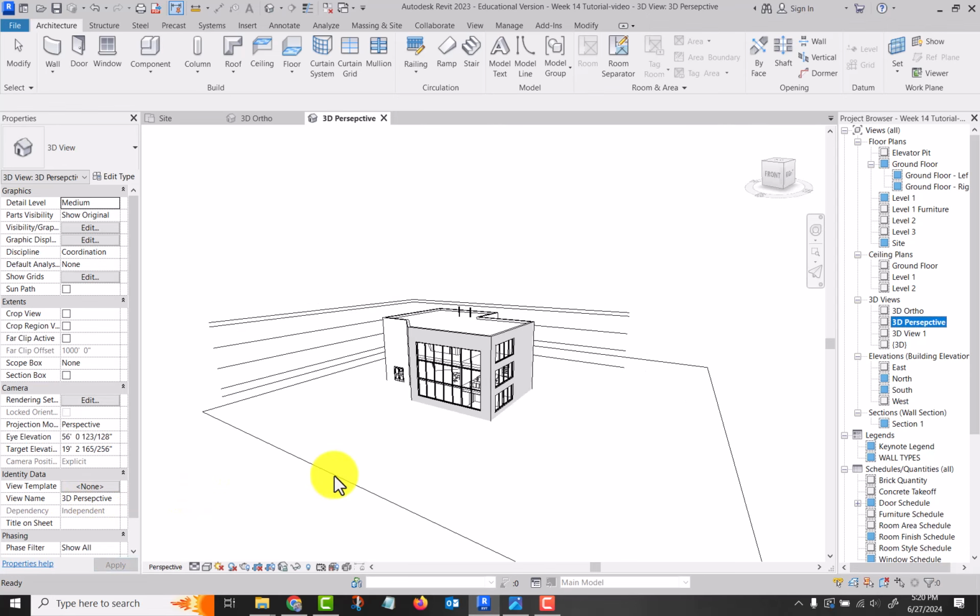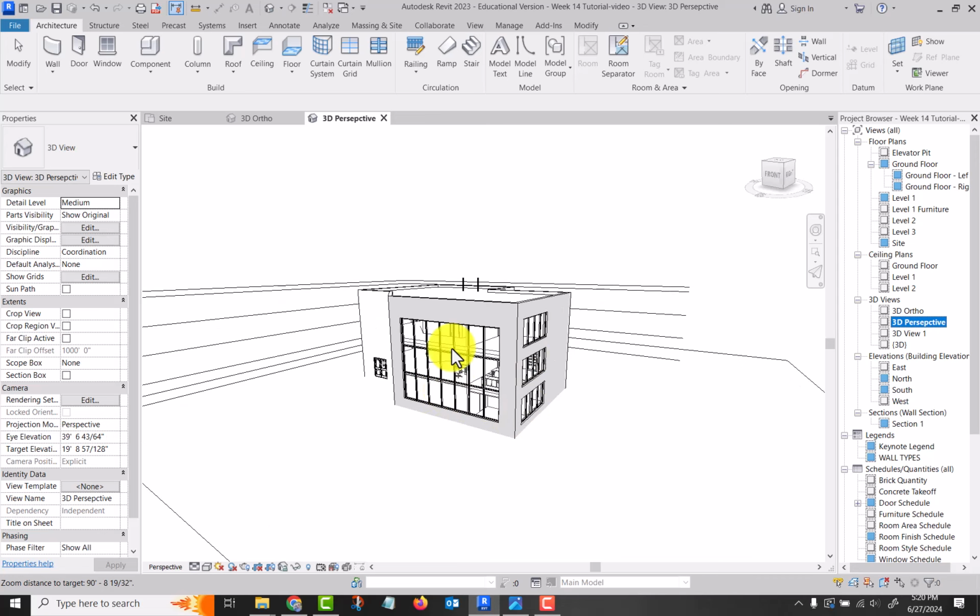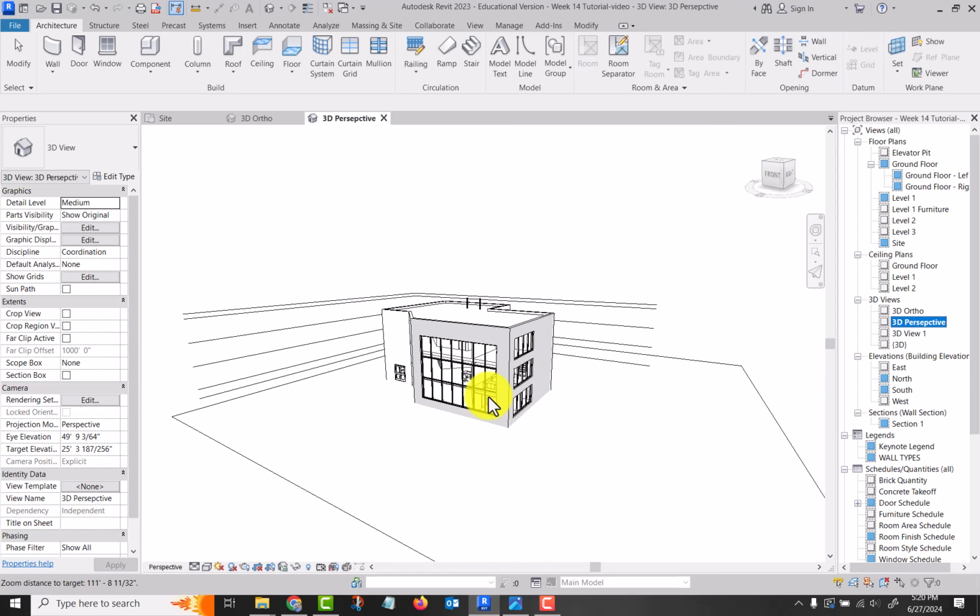And you notice it changes the way it looks because now we have vanishing points in that all of what were horizontal lines here are going to a common vanishing point on the right side and on the left side. And the camera view is always the center of the view. You can adjust the target view in the back, but the camera view is always going to be center of the view once it's set. Okay, so that's a difference in the two. Sometimes you'll want plain ortho, sometimes you want a perspective because it looks more natural to the eye, but it totally depends on what you're doing.